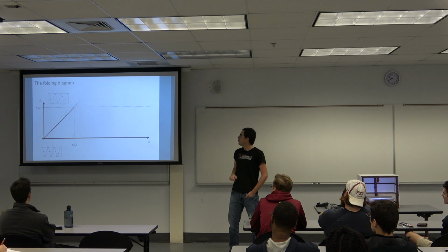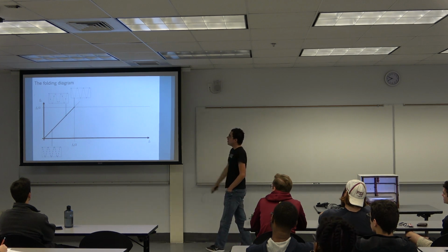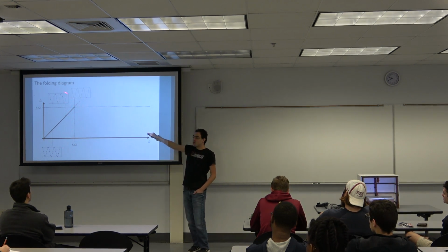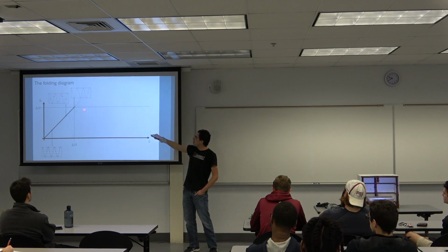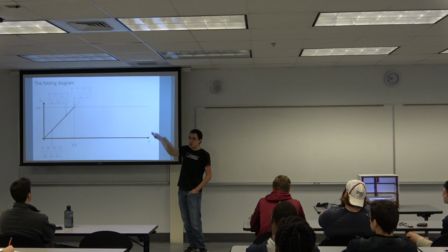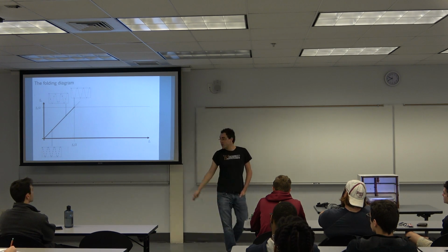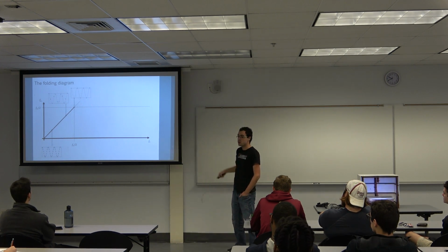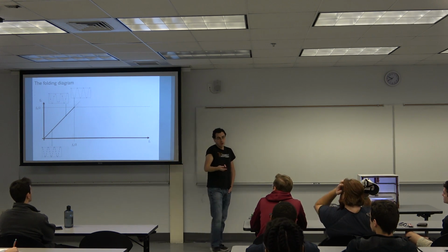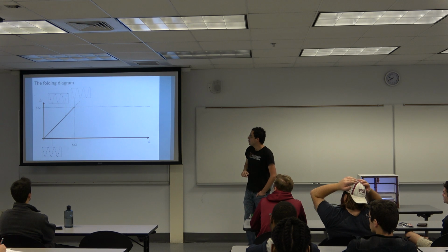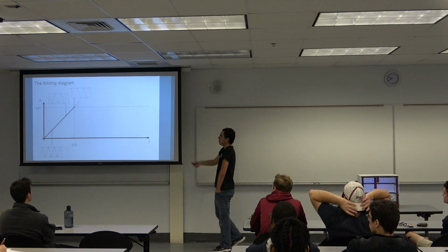If we now match the ceiling frequency with the maximum frequency that you can capture, we get 2 samples per cycle, which means that if we connect the dots, we can reconstruct a triangle wave that resembles our sine wave, and we can still get the frequency right. But what happens if we increase it even further?